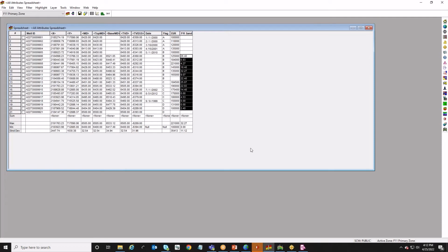Again, just taking those values picked at each well and then summing that over that interval and applying that value to the well there. That's kind of how cross-section is going to interact with Zone Manager data. Picking those intervals, saving that data back in here as an attribute, and then I can take that attribute and, we'll look at here in just a minute, build an isomap of that information that I can then put back into GeoAtlas.